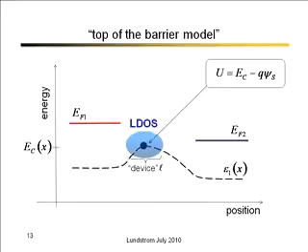So we have some density of states, and we're just going to assume bulk silicon density of states at the top of the barrier. Our self-consistent potential that we apply through the gate voltage is just going to push those states up and down. And we have a small, short region there under strong gate control of length L. That's our nano device. So the overall channel length might be 30 nanometers, but there might be a region of 5 nanometers or so that's strongly under the control of the gate. That's our little nano device.